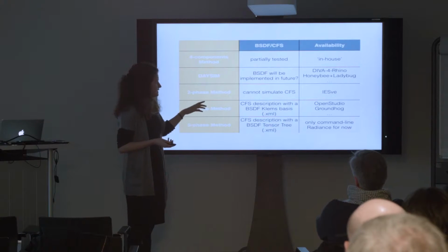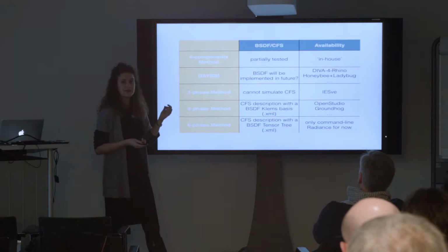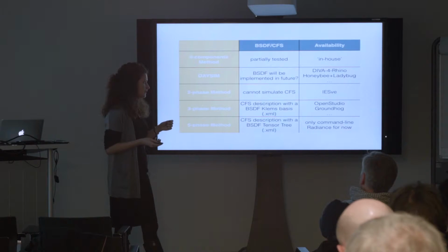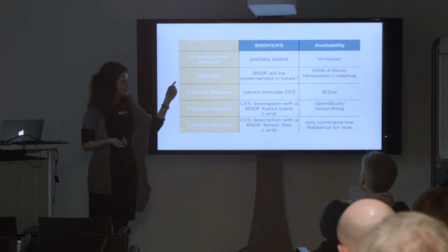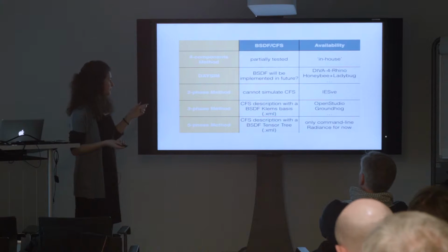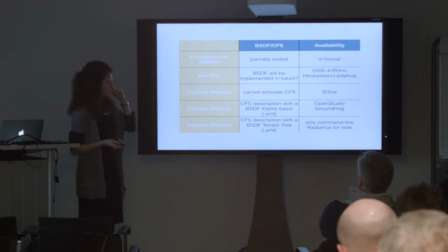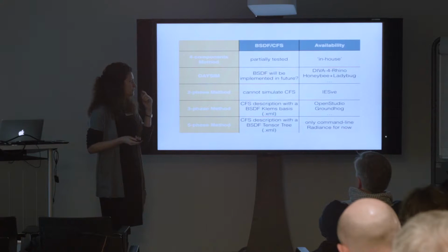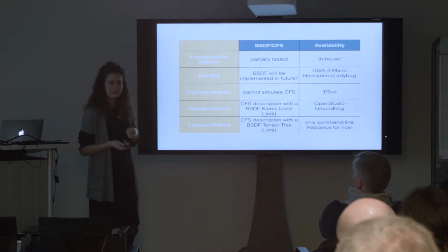And you can find these different methods also embedded in some software, some commercial software or even open source free software with a graphic interface. So for example, DAYSIM, I usually use it through DIVA for Rhino, which is a plugin in Grasshopper. Or the three-phase method is embedded in OpenStudio, while the five-phase is not yet, as far as I'm aware, in any interface. And the four-component method, John has it if you want.